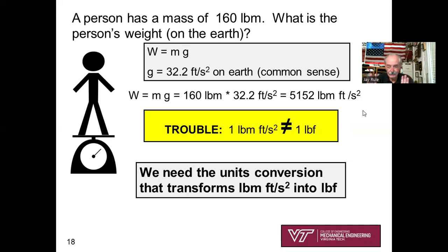Trouble. Rather than being a smart aleck about it, I just want to come right out in a yellow text box and say 1 pound mass feet per second squared does not equal 1 pound force. Please be aware of that. Many students think it does, and they lose lots of credit.